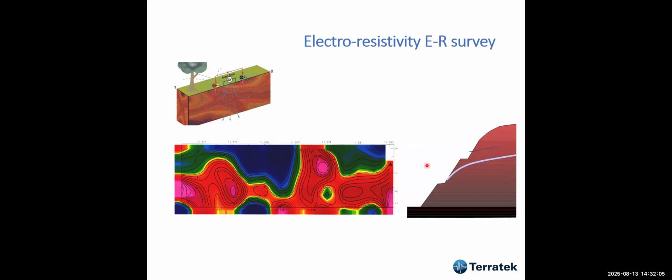you. And this is a case of a slope in residual soils in which we want to discover where the water was. We want to store subhorizontal drains deep into the soil to extract water. And here at the blue areas is where we have the water.